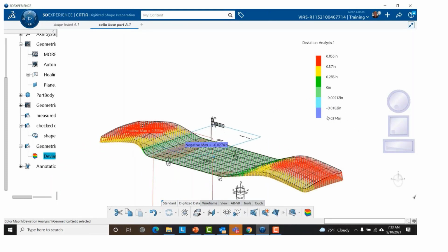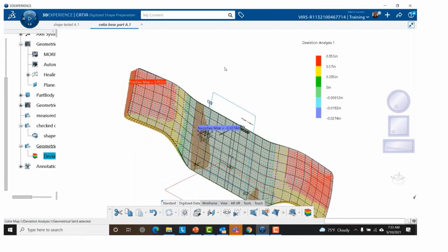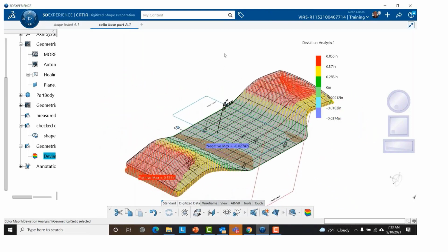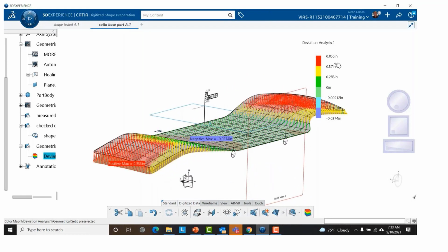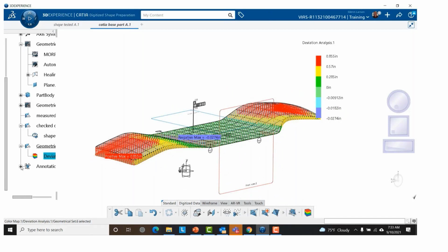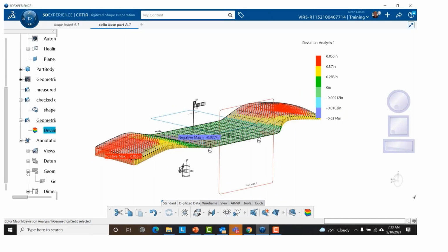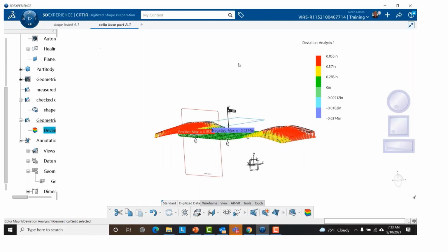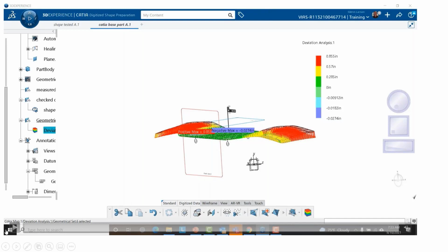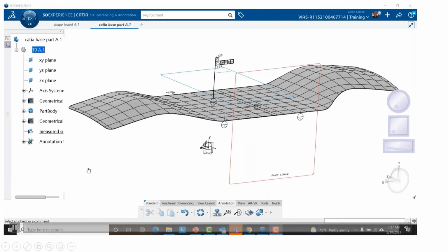This is a great way to check parts. This is a great way to redesign parts and see what's really going on. I know a lot of people are already using CMM machines and have seen data overlaid and things like that, but this is really a way to do it. And you see you've got the GD&T in here, so you can access that as a number and a parameter if you wanted to, and do a parameter study. So that's pretty much what I had for that section.